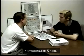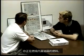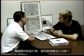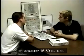No, they'll continue to run for 5 minutes. After 5 minutes, they shut down. You're burning your inner wing tank fuel. When would the transfer valves open up to allow the outer to spill into the inner? When it senses less than 1650.